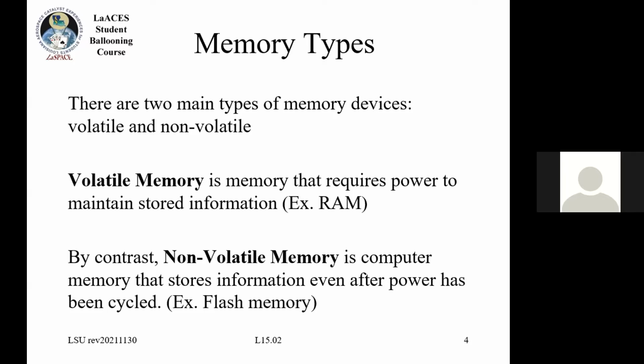That's like the flash memory that your program gets uploaded to in the Arduino. The Arduino needs power to run the program, but as soon as you supply power, it will run whatever the last program was that was stored, because it stores that in the flash memory, which is non-volatile memory.